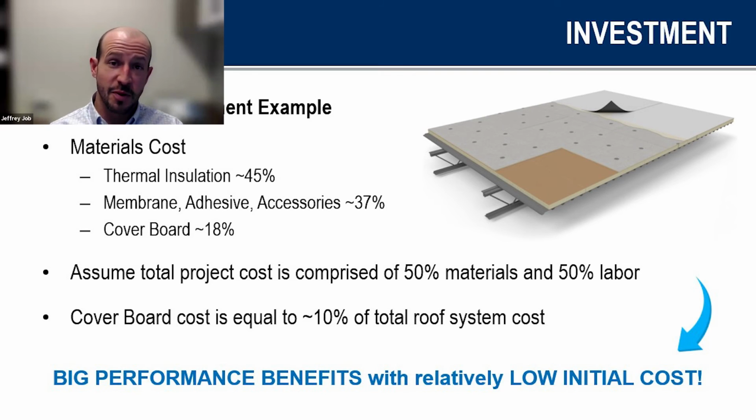It's going to help, especially with your guarantees too. JM, we're big in the guarantee world, and we're going to allow 20, 30 year guarantees. Generally, almost all those are going to require a coverboard because it's going to really add to the longevity of that system. You can do recover applications as well. If you're just doing a recover, throw down a coverboard and go right over the top of it with another membrane.